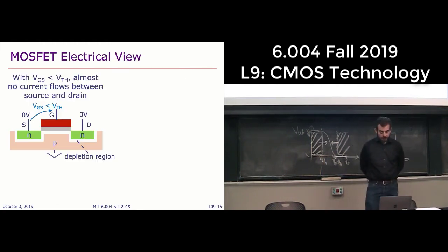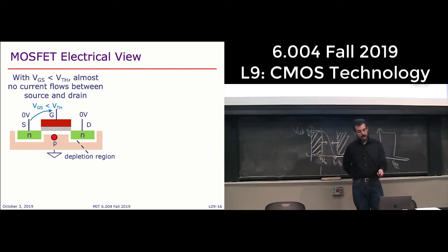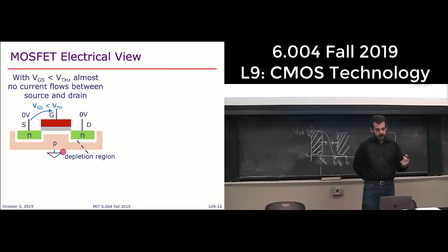So what happens is, this silicon slab is doped with different materials. We have an N-type semiconductor here because we add dopants like arsenic that essentially add electrons. And then we have a P dopant here, something like boron, that makes this part of the silicon add holes.